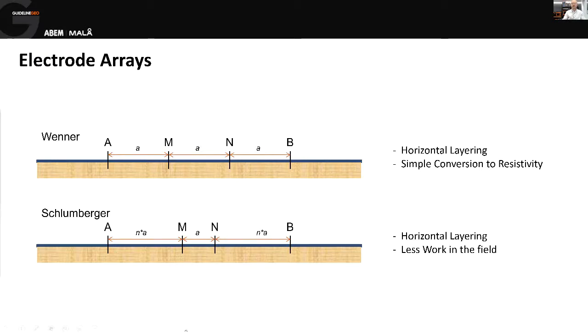And then our choice is whether we want Wenner or Schlumberger. Wenner has a better signal to noise ratio. If you're going very deep, Wenner would give you the best chance of getting reliable results at the deepest levels. But the downside is, for a Wenner measurement, all of our electrodes need to be equally spaced. So every time we take a measurement, we have to move all 4 electrodes. If we choose the Schlumberger, we don't have quite the same signal strength, but we have the advantage that most of the time we only need to move the outside electrodes, the ones that are injecting current.